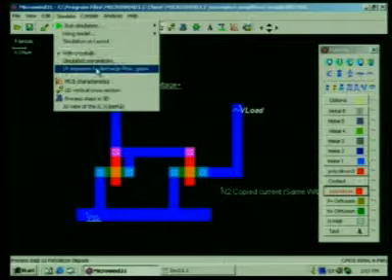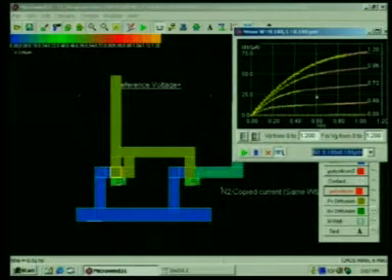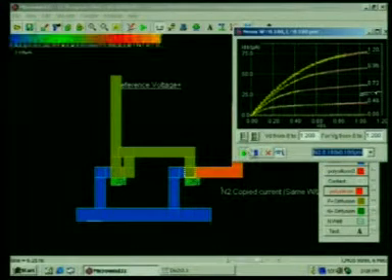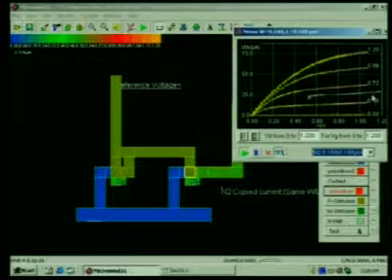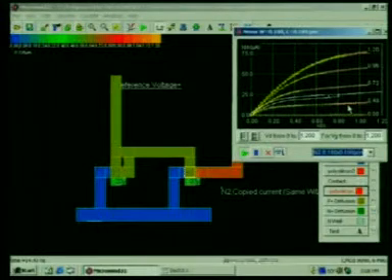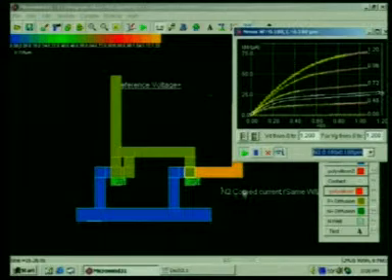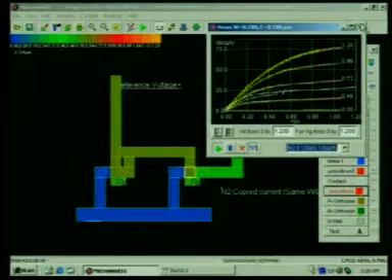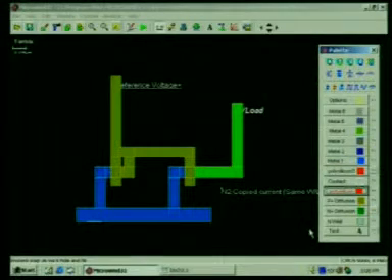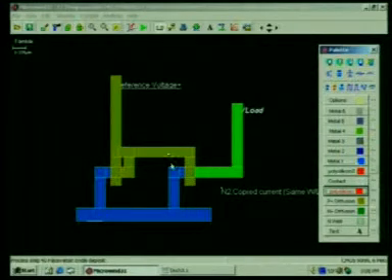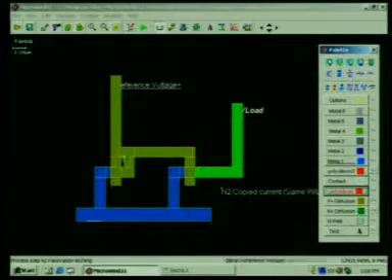See this, simulate, and then simulation on layout, select the node voltage at N2, after that simulate this one, see this at this 0.60, this is the reference voltage applied at the master. So, here my current will be copied and it will take some time for stabilization. So, definitely it will be approximately this. Suppose anybody wants to use this current mirror as a multiplier. So, what does he have to do? He has to just double this one, that is very simple, that current will be just doubled.